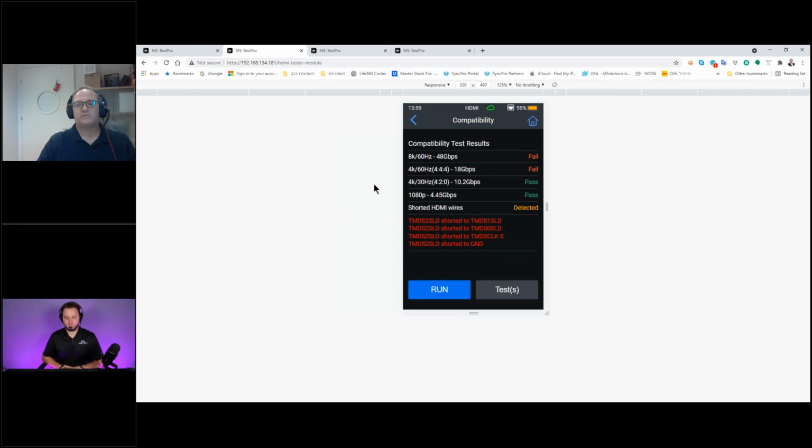Sure. On the infrastructure, there is a variety of manufacturers, and not all of them are good on the category cables. How many CCS and CCA cables are you familiar with, which come from the Far East, which are copper-clad aluminum? You have a core of aluminum inside the wire, which is covered with a copper layer in order to show that it is good. Those category cables will be detected immediately by seeing a very high resistance on the line.